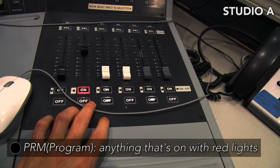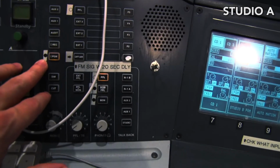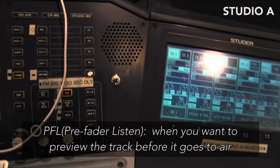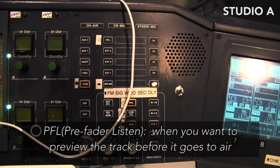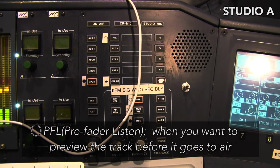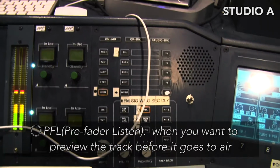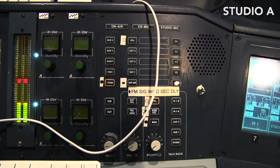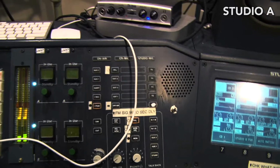Program is anything that is turned on, our red lights. Any of the armed tracks, if you have this program button set, they'll come through the mains. We have another feature on this board called PFL, and it stands for pre-fader listen. And that's how you would listen or cue something up if you want to preview the track before it goes to air. So you can play it to yourself without playing it to the radio audience and make sure it's the right thing, or it sounds good, or you can audition it to see if there's any swear words or anything like that. That's the PFL feature.